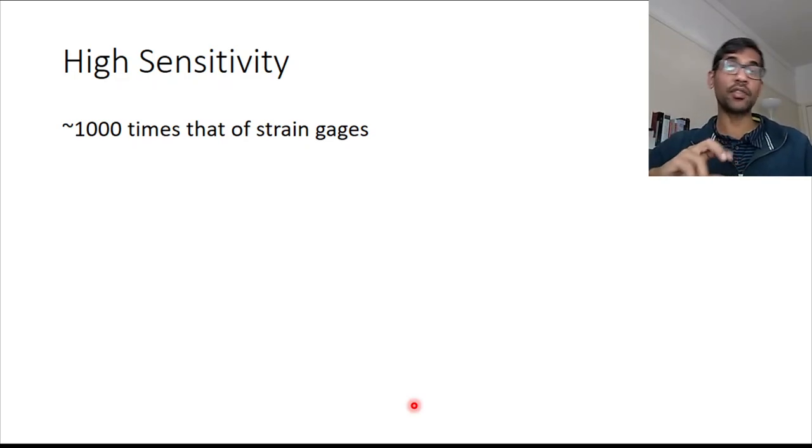And that's why piezoelectric crystals are so popular in spite of having a non-existent DC response, right? We cannot measure constant strains, but for changing strains, piezoelectric crystals have a very, very high sensitivity compared to strain gauges, which are a very common kind of sensor.